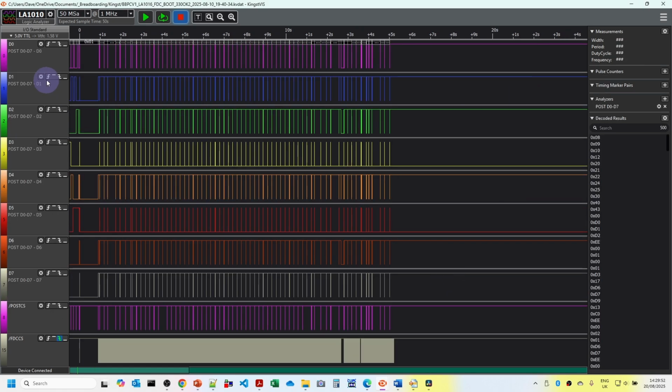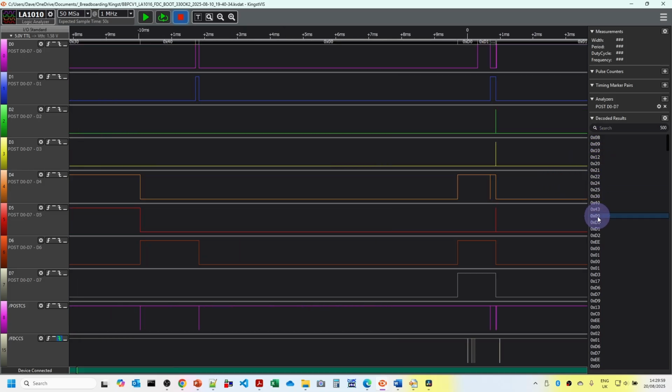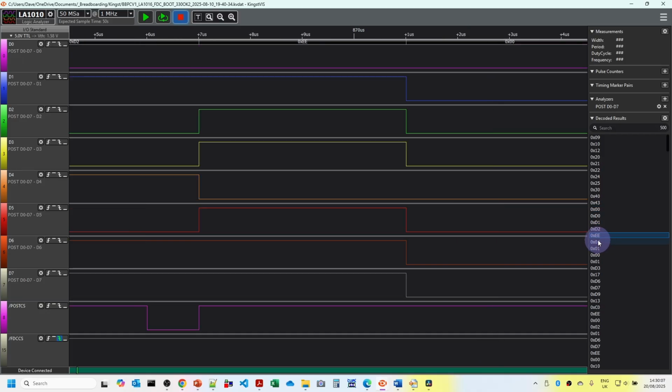And then the power on self-test port output actually shows the postcode, so we can see the postcodes going down here. 0 means trying to boot the operating system. And then the D0, D1, D2, these are my debug messages. EE indicates the disk parameters being sent to the drive for seeks. And then we can see all the way down here, there are actually quite a lot of individual disk requests as the operating system actually boots up.